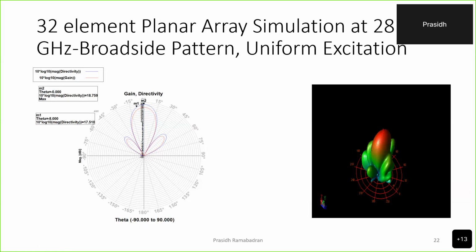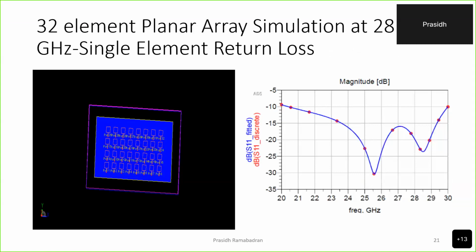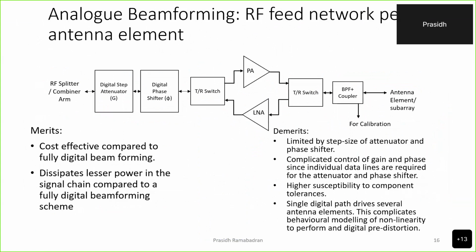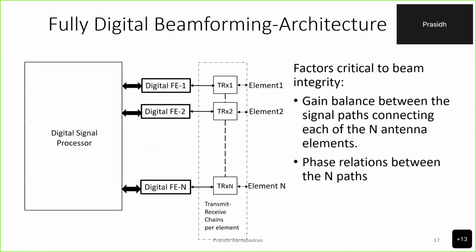So one of the ways to reduce the side lobes is by providing a non-uniform excitation. Let's say instead of a rectangular spectrum, we have something like a cosine spectrum, or a cosine on a pedestal, or a trapezoidal spectrum. Now, of course, beamforming is not the focus of the session, but I'm just touching upon this, mainly for the upcoming slides.